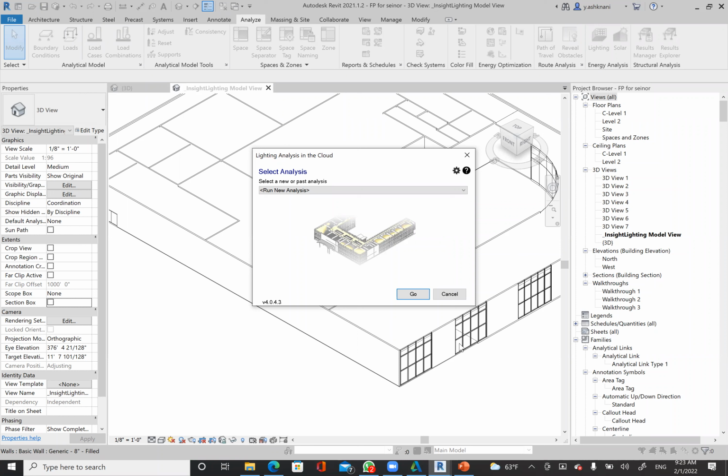Yeah. First thing we need to do is put all the lights, put all the receptacles. Then only we can put panels. After we put the panels, then we do looping and circuit creation, and when we do circuit creation, automatically we will get the panel schedule. Yeah, you showed me in the Word file the last time.